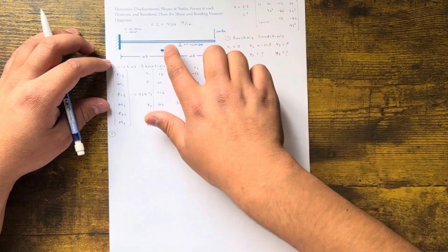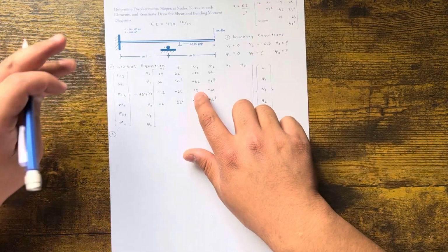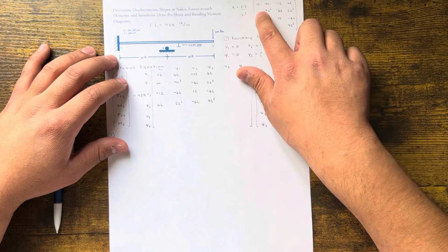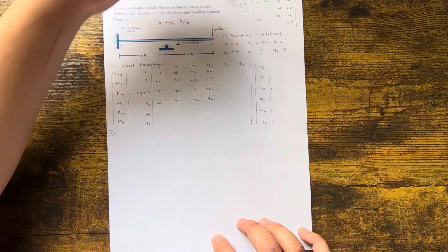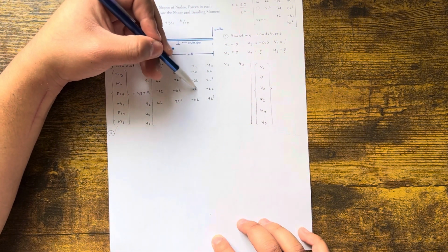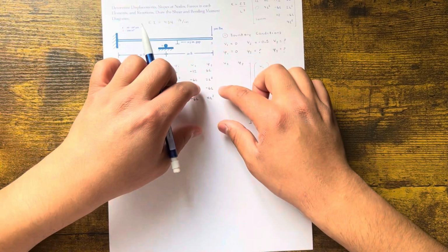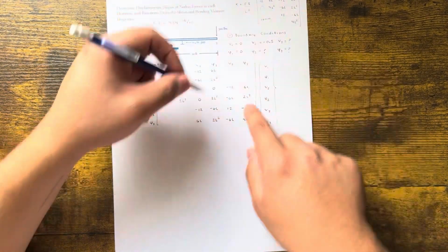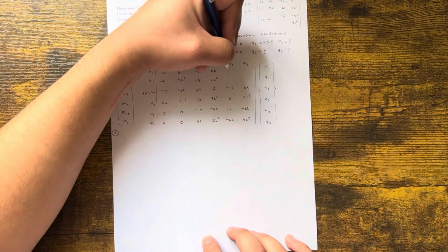All right, now let's go ahead and do the same thing for element 2, between node 2 and 3. So 12 gets added to this 12, and then 6L gets added to both of these. It's symmetrical, right? So that's also a 6L. And let me use my pencil. This spot here is a 6L because it's symmetrical. So these two go to 0. This will be 24. And then 4L squared plus 4L squared, that's going to be 8L squared. And then I'm also just going to fill the remaining part of the matrix, okay? All right, so I want to go ahead and edit it, right? I just put this little stiffness matrix here, no big deal. And the rest becomes 0, right?